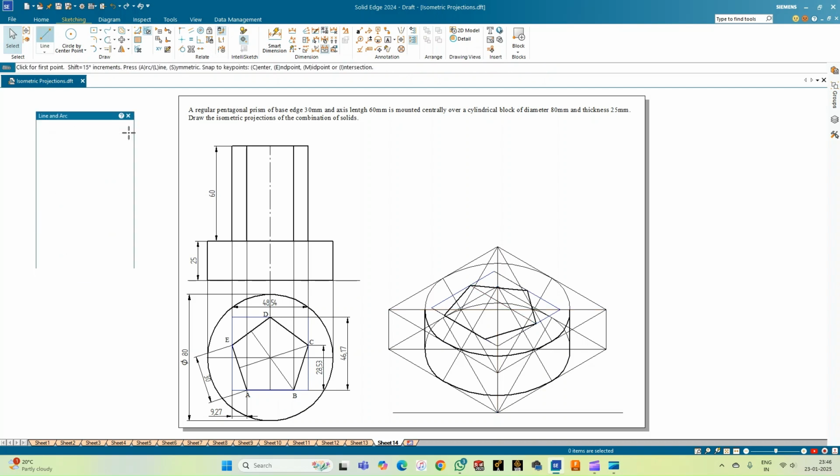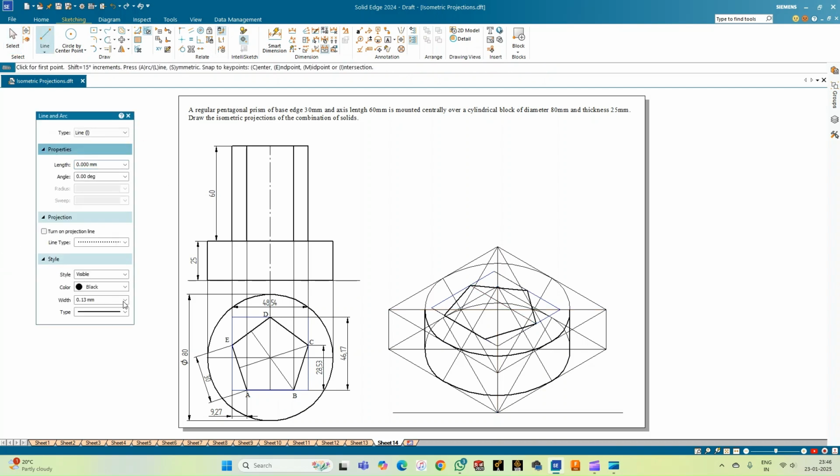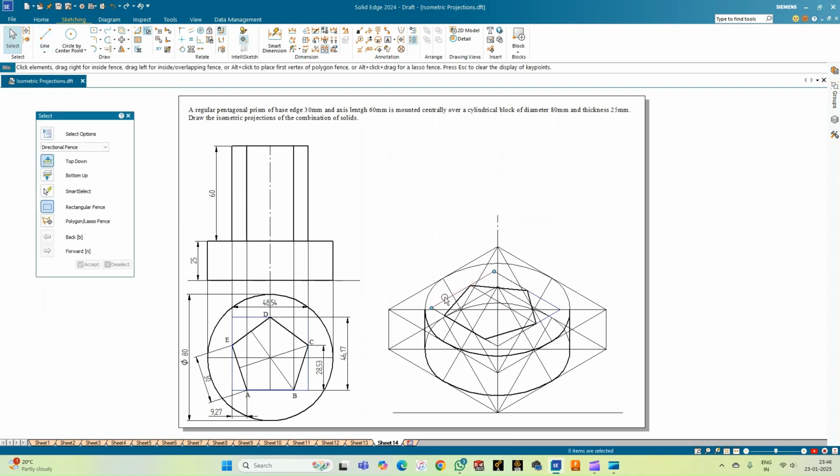I'll go back to the line option, select point 13. The type is axis line. So I get the point of intersection. From here I'll take the true scale of 60. Remember, it is only in the system that we are doing everything in the true scale, and at a later stage we are going to reduce the scale. In the manual construction, from this point count ISO 60, that is 6 boxes in the isometric sheet. Now I need to repeat the same procedure.